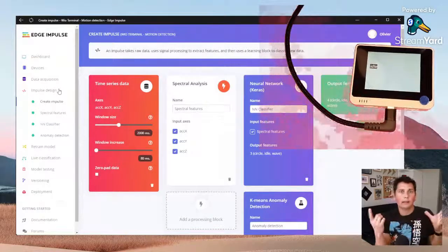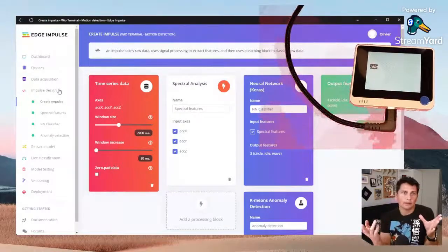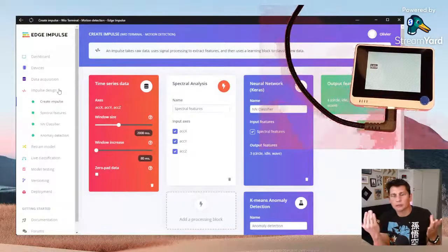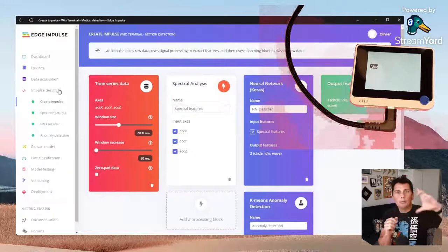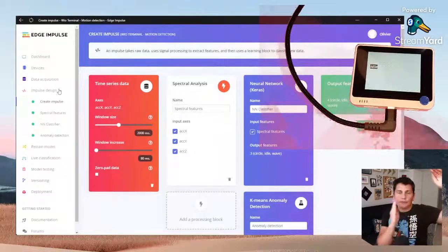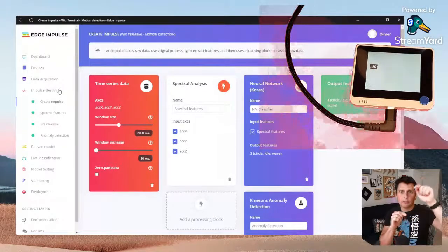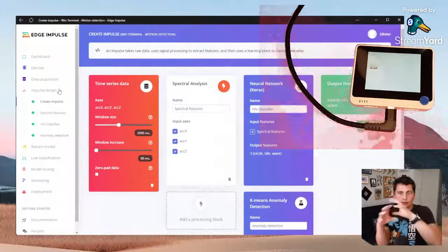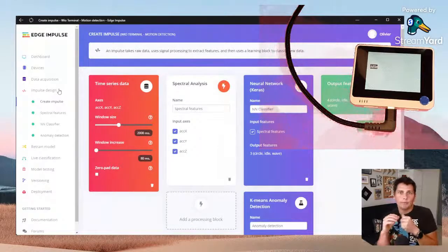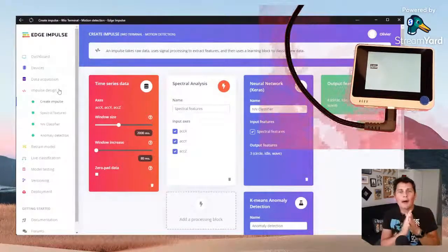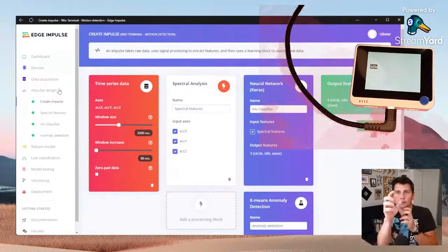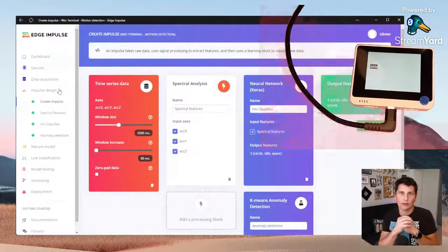One is I detected a circle, one is I detected a wave, one the device is idle, and another one we'll see is there's an anomaly has been detected. And so you come with a bunch of data, and then you define different levels in your neural network, and each of them has a lower number of neurons. You trickle it down. And there is a way of determining how this reduction is, what each of these neurons are really about, and that's what the neural network block is about.